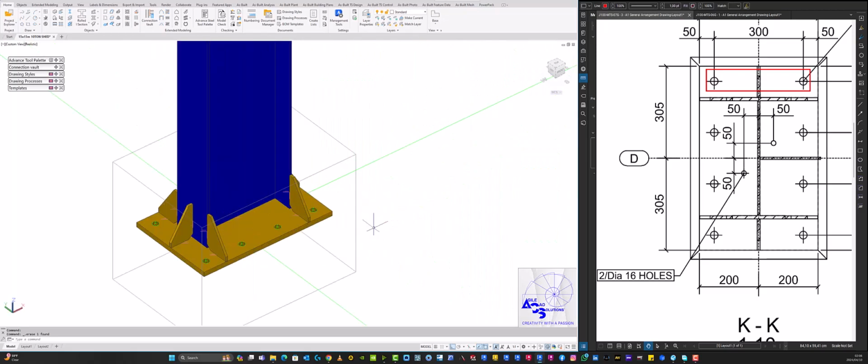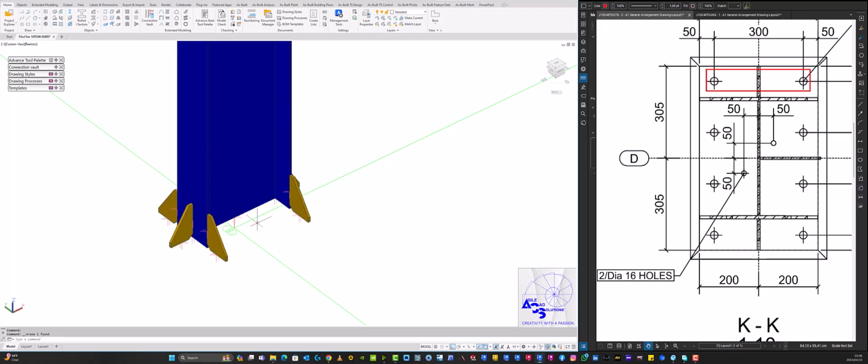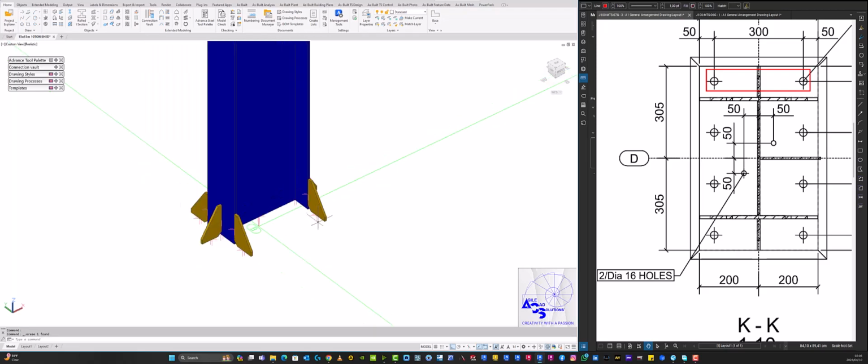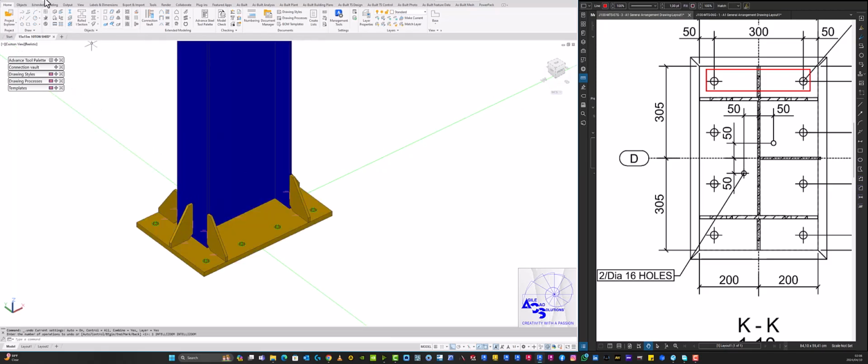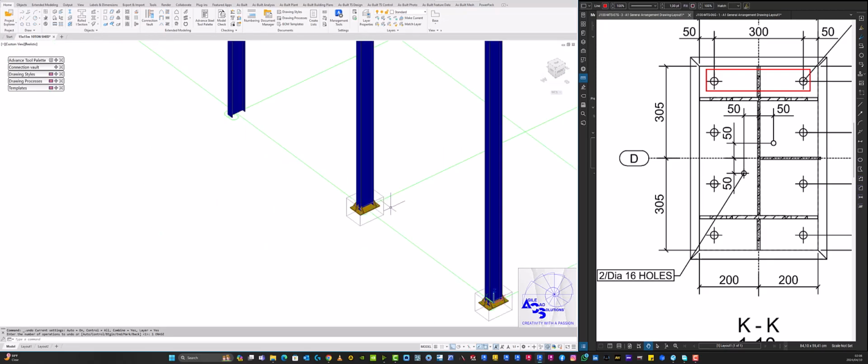You don't delete the joint box. If you delete the joint box, you have now deleted the rules that join these things. So if you want to delete the base plate, you have to do it manually, selecting each and every element and deleting manually. That's not what we want to do in this case. Let's skip that, let's undo that.